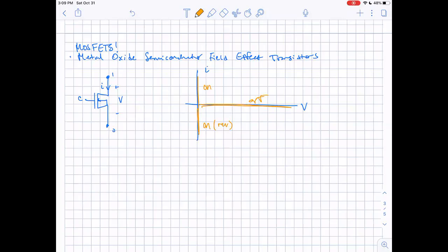When it's operating in the reverse circumstances, it can block positive voltage and it acts as a body diode, which means it has a built-in diode that comes from shorting the substrate of the MOSFET to the source of the MOSFET, which adds an extra PN junction.